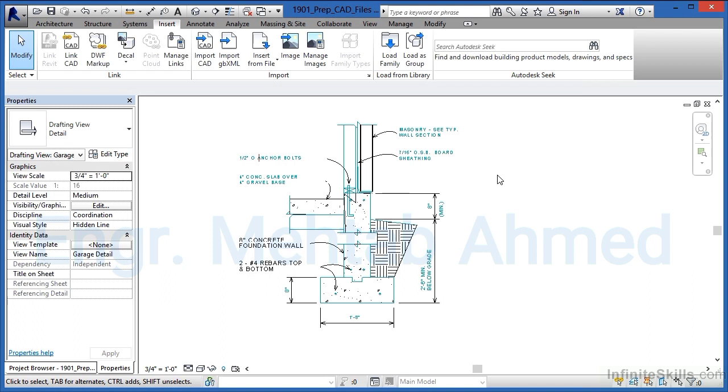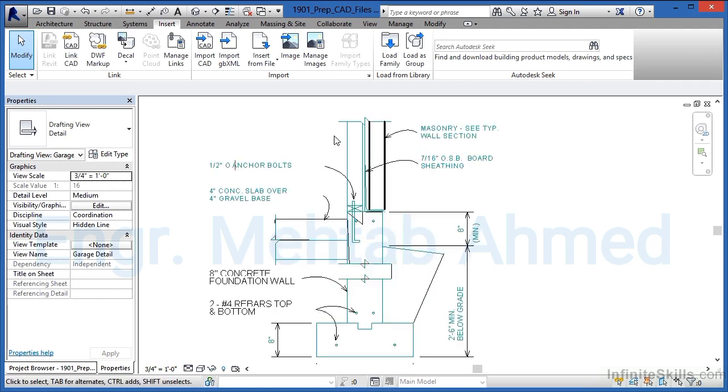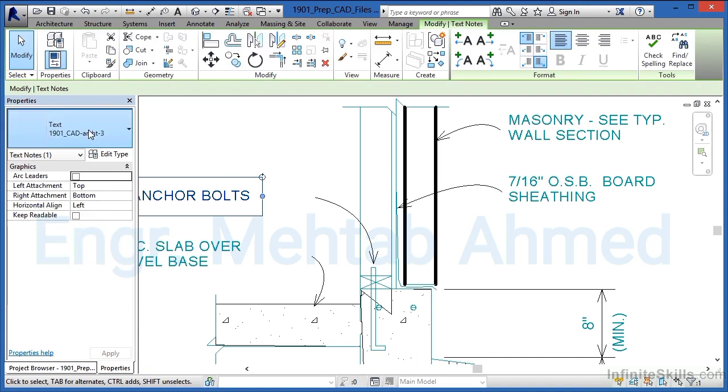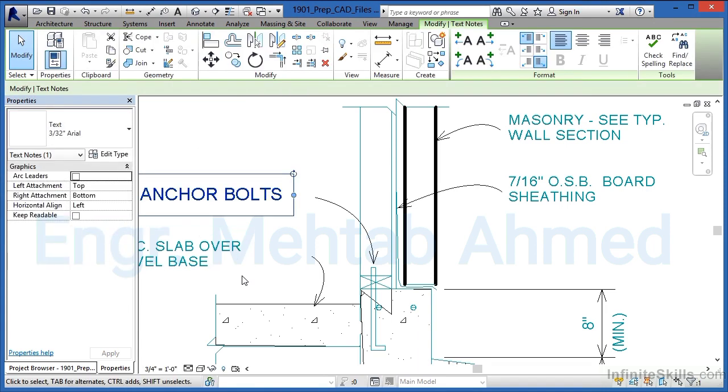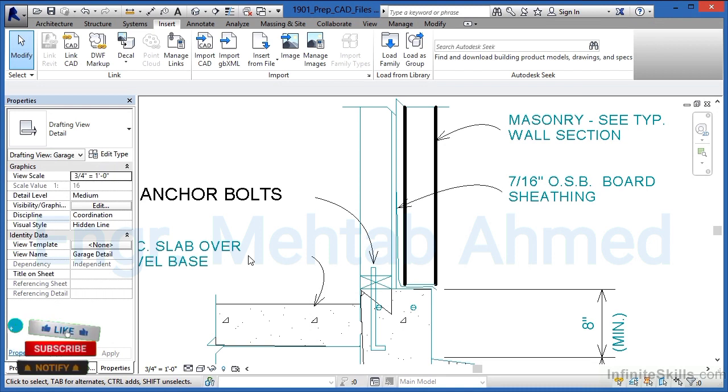Autodesk once said that about 85% of all the issues that they have inside of the software program, if that Revit file doesn't want to open, if Autodesk gets them, they will strip the AutoCAD information out. 85% of the time, that's what's causing the issue inside of the Revit file. So it gives you a little bit of a background: bringing in this CAD information is fine, tracing over it is fine, but it makes more sense to get rid of it or select individual pieces of information and turn it into true Revit entities because it'll look better, meet your standards, and also add to the stability of your Revit design.